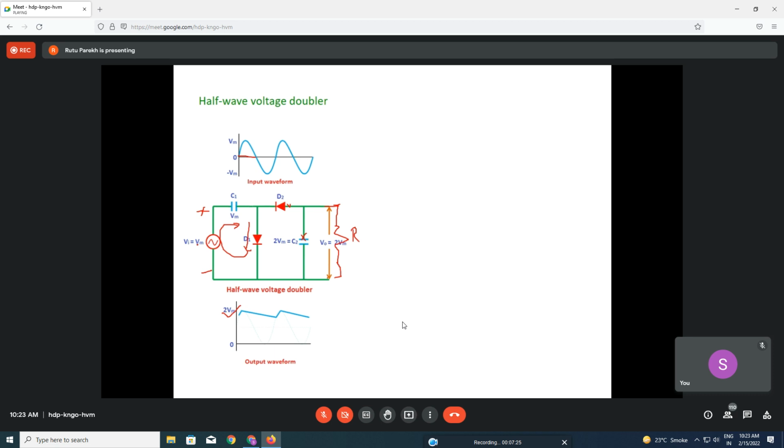Yes. So now if this is plus and this is minus, the current is flowing and it is charging this capacitor with the polarity plus here and minus here. You are giving a potential at this plate, so the positive ions collect here, and accordingly the negative ions will collect here, and it will charge to this peak value. If the peak is Vm, the capacitor will charge to Vm with this polarity, plus and minus. Is that okay? Yes, sir. Very good.